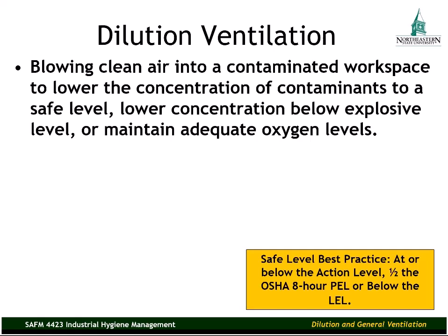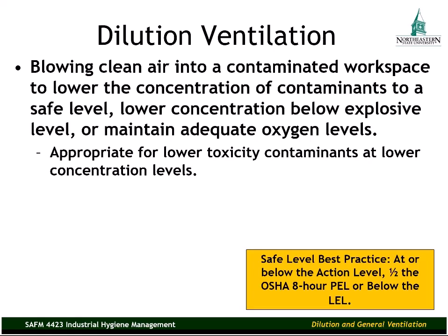Now, dilution ventilation is most appropriate for lower toxicity contaminants at lower concentration levels. If we're in a work environment where we have high toxicity contaminants, or we have high concentration levels, that's probably a situation where we should be using local exhaust ventilation.